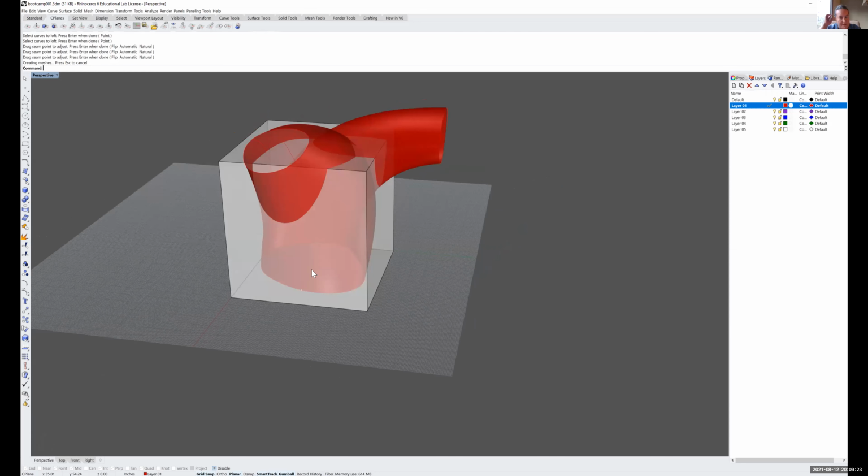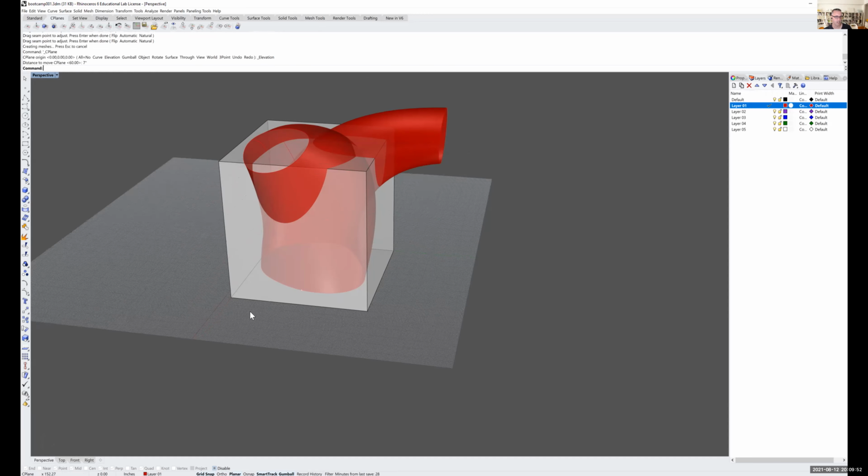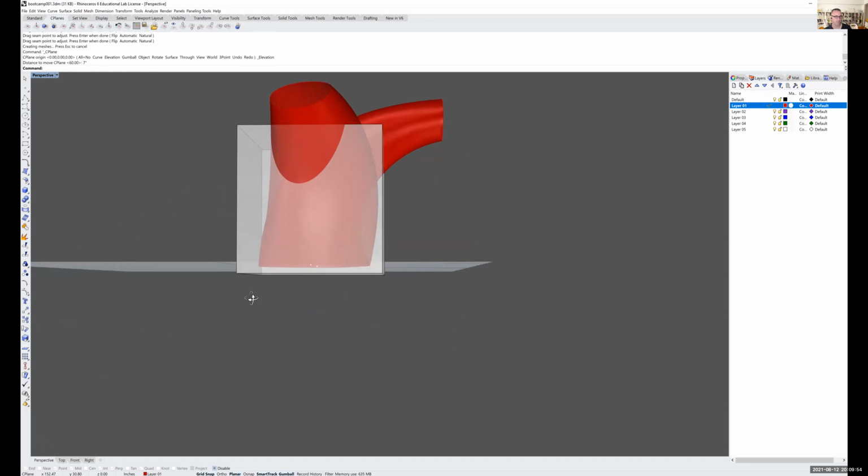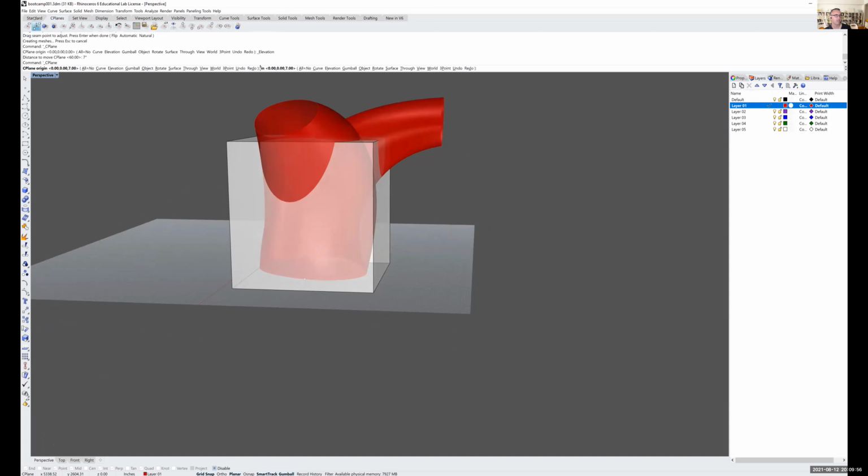So then you can change the second box under the CPlane tab, which allows you to change the elevation. And I wonder if there's also another way. Let's see what happens. So we can set it with a dimension. It's always going to be perpendicular to where it is. So if we actually wanted to do it at 7 inches, we could set it to 7 inches. If you want to set it back to 0, you could type 0.